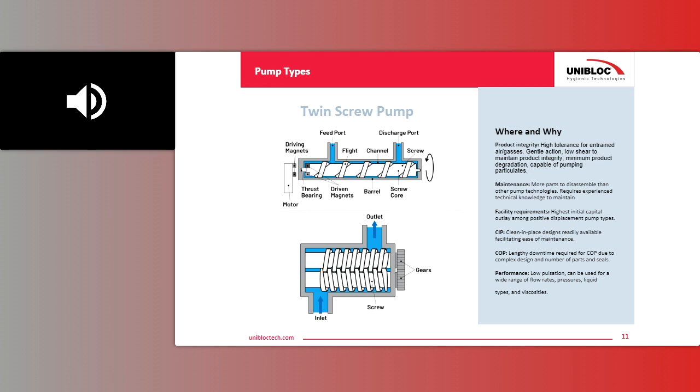The other big benefit of this technology is that a lot of times it's referred to as two pumps in one. It is a pump that can pump a thin, clean liquid like CIP solutions, but you can also pump the product, which is typically more viscous, through there, because of its speed range. These pumps are PD pump technologies, but they can run at what we call centrifugal pump speeds. So these pumps can run up to 3,600 and 4,000 RPM, depending on the brand. That gives you a wide range of scalability.